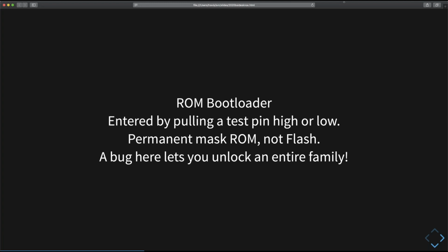So the cost of patching this is that you need to begin manufacturing new chips of every affected item in the family, which requires a mask revision. So you're looking at about a minimum of $250,000 per unique model number in the family. So in the case of STM32, they would need to do this separately for the STM32 F407 and 417 and 207 and 217 and so on. So these bugs live a very, very long time.